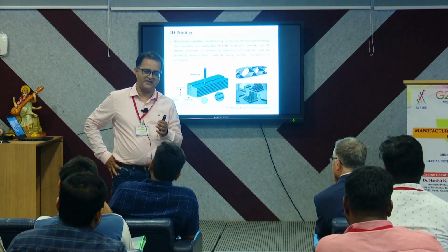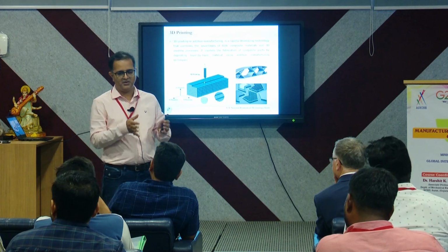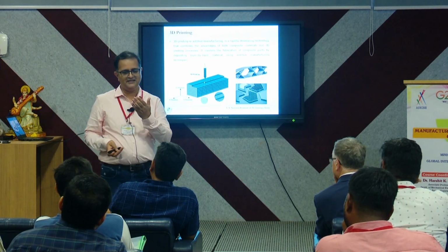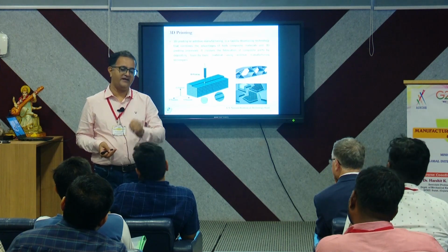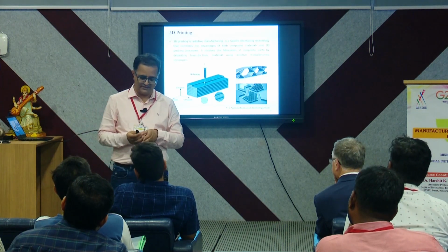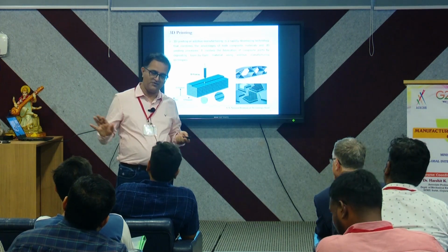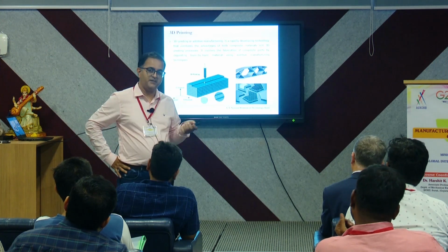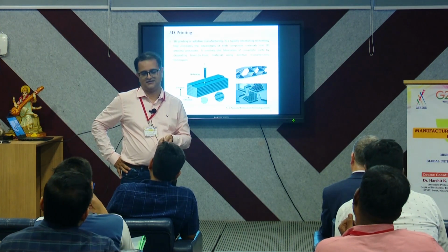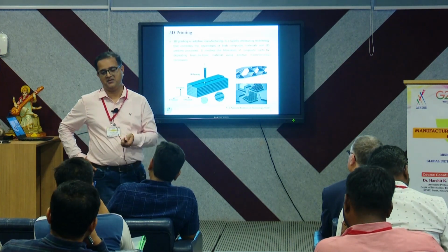So whatever space there is, when you are pulling this resin inside, it's not really pulling, but because of vacuum, the resin easily gets into it. So the chances of air entrapment that exist in the other process are reduced. Otherwise, this is capable of making any size of part, same as the vacuum resin transfer. But there is a chance that when you are using multiple layers of fibers, air may remain inside.